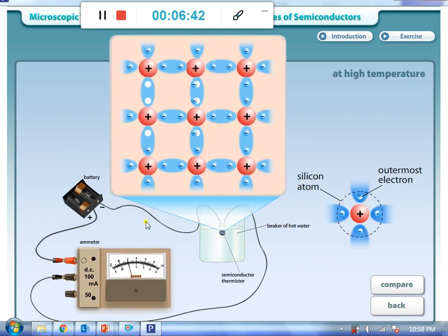But why? Because when you give it energy, it will be easier to have the holes, to let the electrons fill in the holes, easier for the electrons to move around. It means that the resistivity will be decreasing, easier for it to conduct electricity. As a result, at higher temperature, resistivity will be lower, resistance will be lower, in semiconductor.